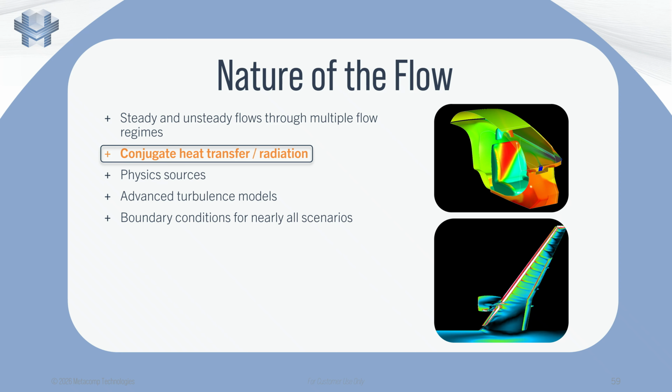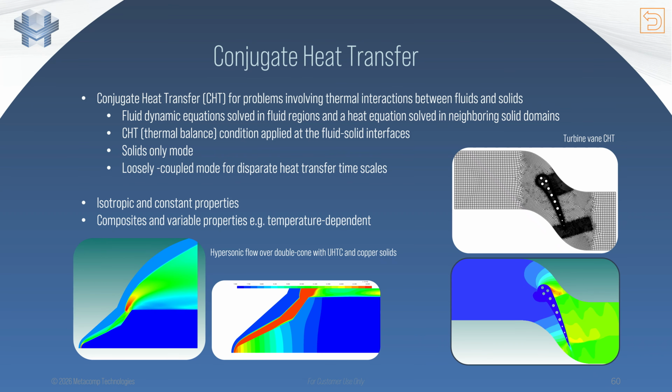Conjugate heat transfer simulations are essential for accurately modeling heat transfer between solid and fluid domains, particularly in engineering applications where thermal interactions play a critical role. In CHT simulations, fluid dynamic equations govern the behavior of fluid regions, while heat conduction equations are solved in adjacent solid domains. A thermal balance condition is enforced at fluid-solid interfaces to ensure accurate heat exchange modeling.